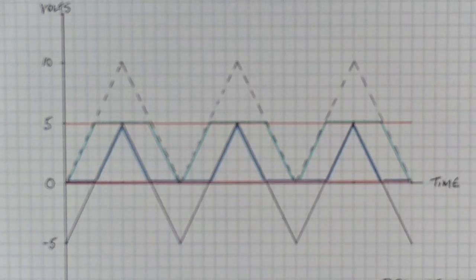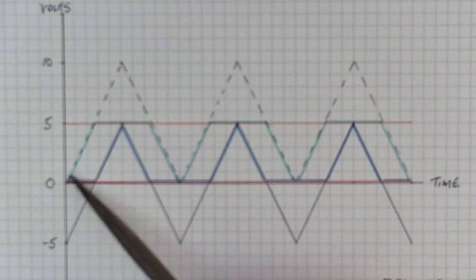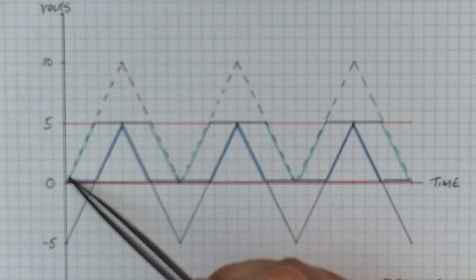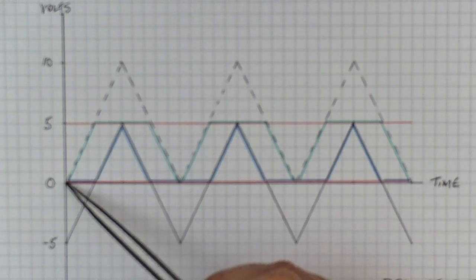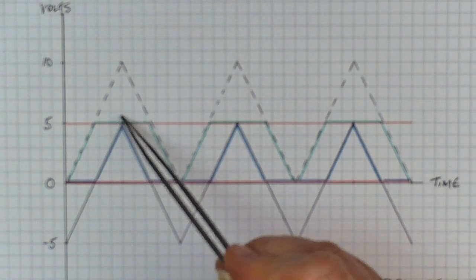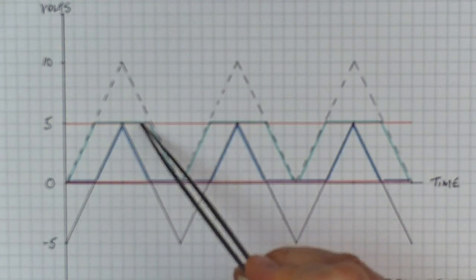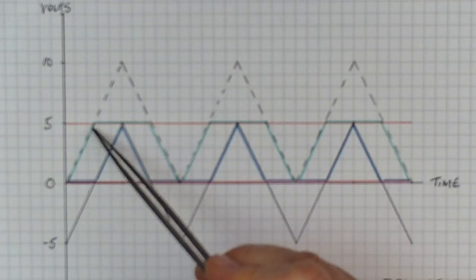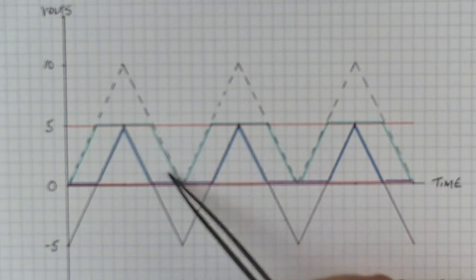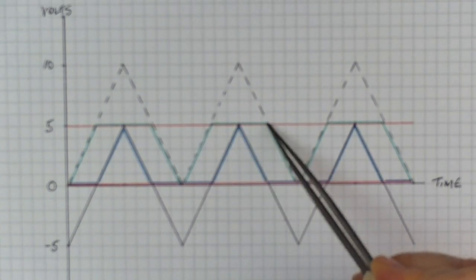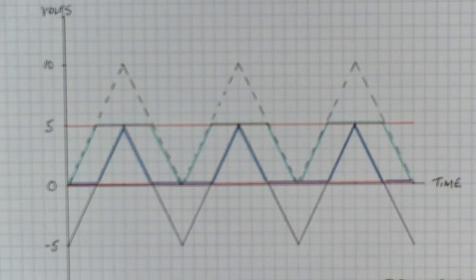Okay, I hear you say, what about unipolar LFOs in Eurorack? Well, they would again go from 0 to 10 across the full 10 range, with the lowest value at 0. But we have the same problem here in that when it's above 5 volts, Rorschach is just pinned at its top value. So we have this green line now where it goes up, sits at its top value, down, up, sits at its top value. So again, it's the same problem with unipolar LFOs.